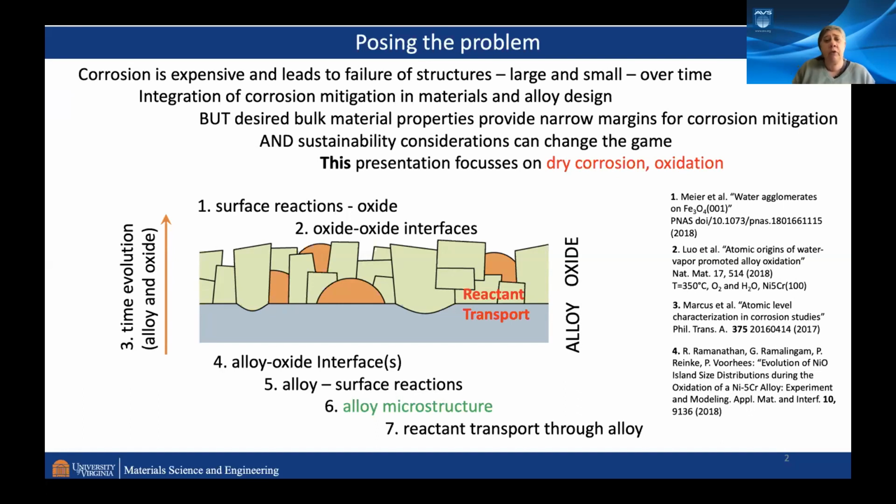If you think about corrosion, the traditional way to think about it is, okay, we need to make an oxide or nitride or another layer on the surface which mitigates the detrimental attack to the alloy of whatever chemical environment my material experiences. So in general, if you work in air or in aqueous environments, this will be an oxide.